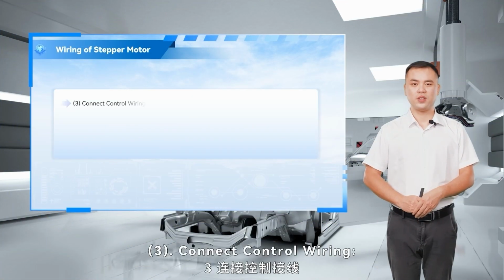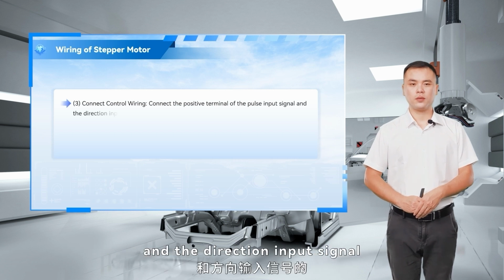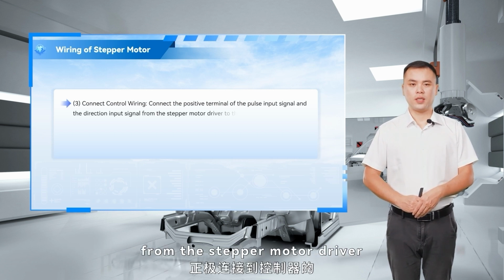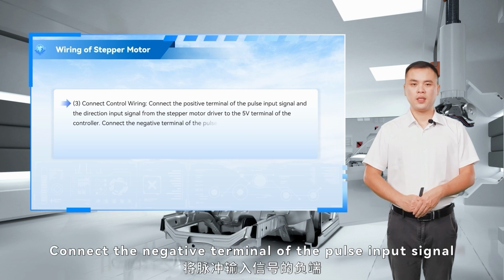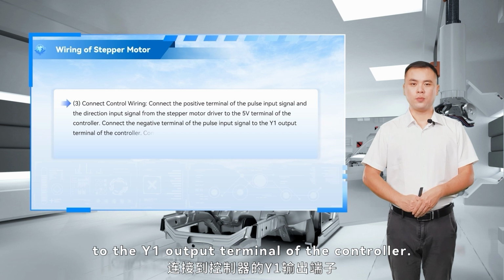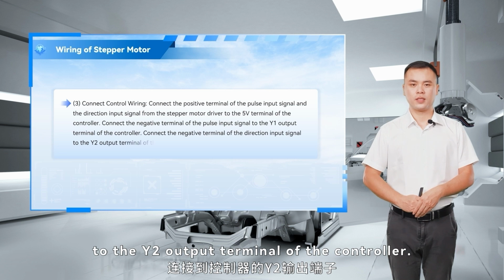3. Connect control wiring. Connect the positive terminal of the pulse input signal and the direction input signal from the stepper motor driver to the 5 volts terminal of the controller. Connect the negative terminal of the pulse input signal to the Y1 output terminal of the controller. Connect the negative terminal of the direction input signal to the Y2 output terminal of the controller.